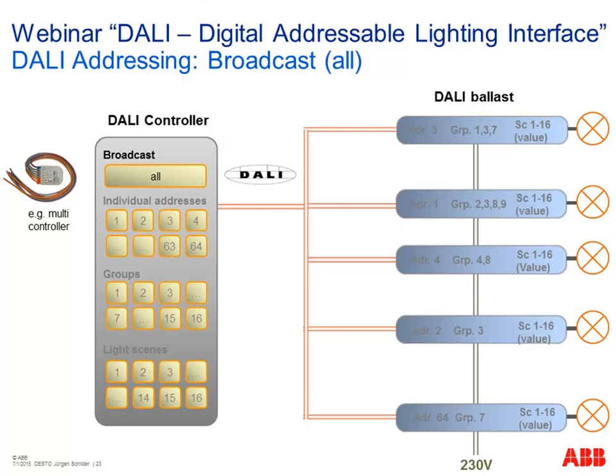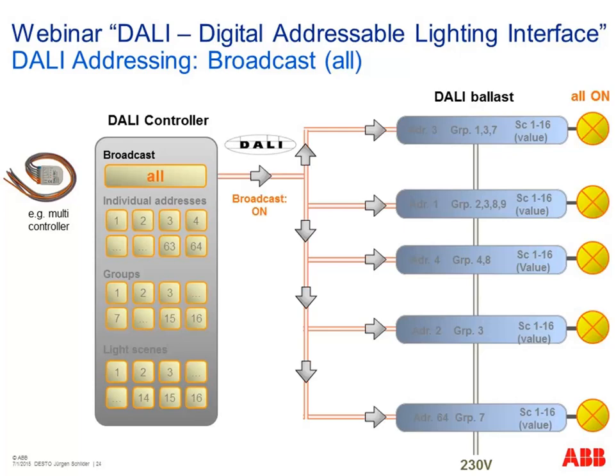And this component, for example, could activate a broadcast command. A broadcast command is always possible in DALI. It's an additional feature, operating all DALI ballasts behind at the same time, switching or dimming, whatever you want. So all on in this example. Broadcast command, always available.